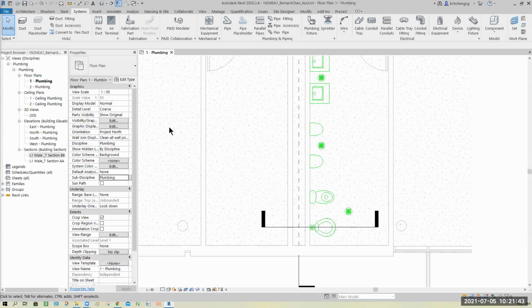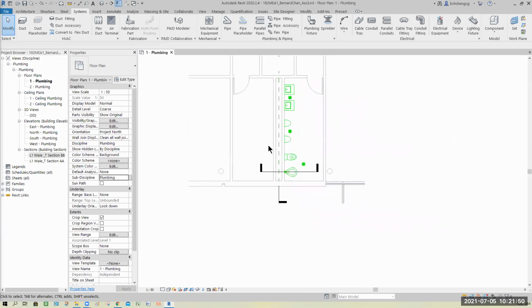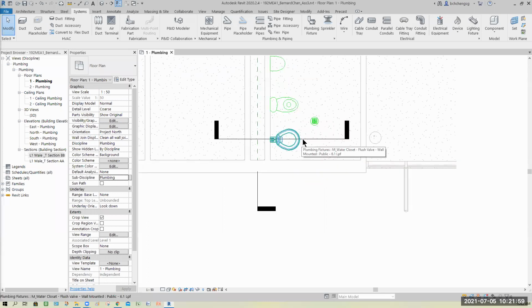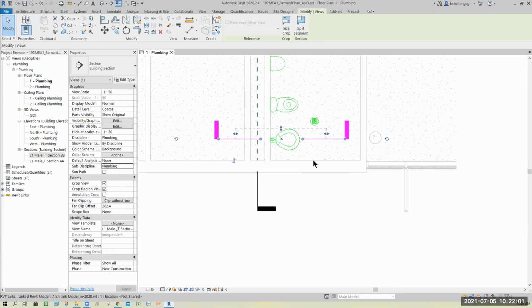Okay, I believe you guys are testing it out. Hopefully. Okay, so once you have all, these two generated. Same thing. If you don't want to see the line cut this way, you can break it also. When you break it, one thing I need to highlight: how to ensure that this section line is the center of this location.